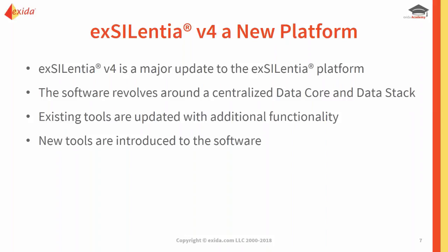I was actually looking this morning at a PHA that was done by one of our customers in a spreadsheet, and we were trying to figure out how can we easily get that information over to a layer of protection analysis. How can we get that information easily over into our alarm rationalization software, SILalarm? And the answer was, well, it's going to be a big manual task to do this. In this case, there wasn't even something that was easily importable. Causes and consequences were all mixed in the same cell within the PHA.